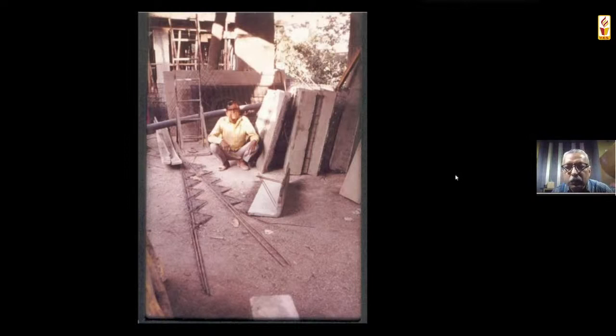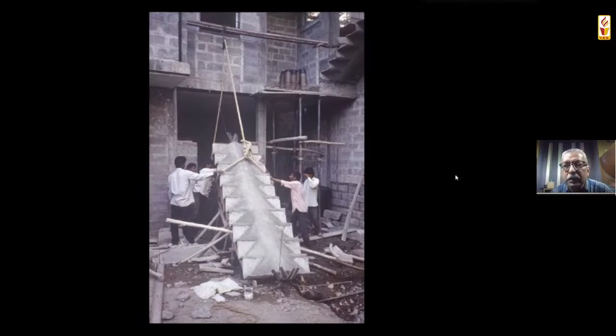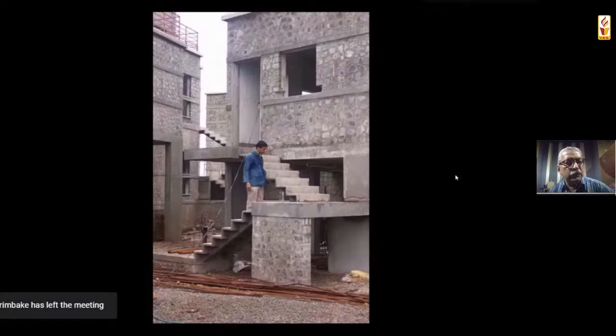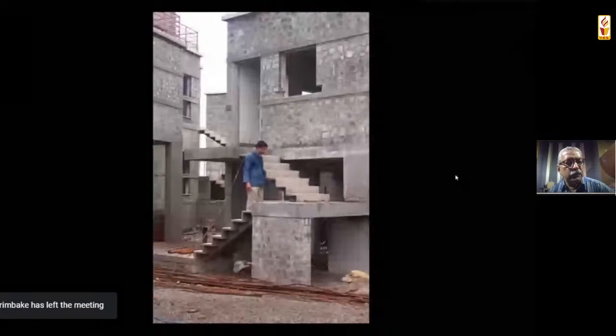And then what he will do, he will make a ready-made staircase, like a precast staircase. So one staircase is already up there on top, you can see. And this staircase they are trying with very simple human labor, no machines are required. And then this becomes kind of ferrocement, ferrogami, and this poured rubble masonry together. So load-bearing walls of poured rubble masonry.